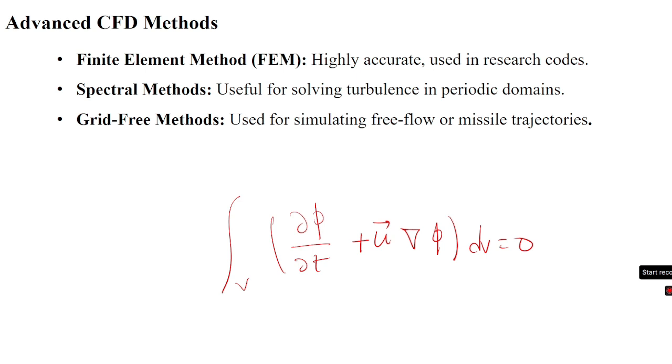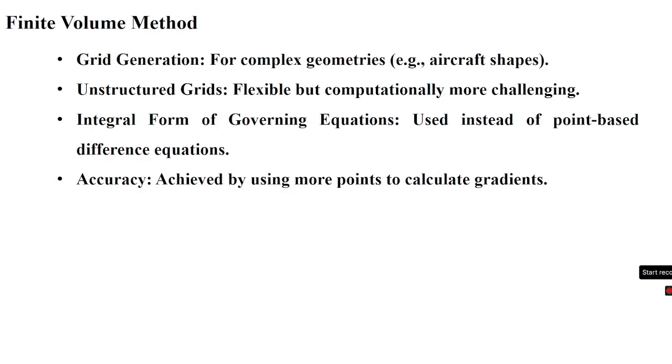So finite volume has some advantages. It can handle any geometry including irregular or complex domains. FVM, the finite volume method, is suitable for aerospace simulation with slats, flaps and other complicated shapes, and can use various types of cells like hexahedron, tetrahedron or prism. But it has some limitations, limited accuracy compared to the finite difference method. Lower order accuracy because it only uses neighboring cells, with no information about distant cells. The solution is often less accurate than the structured grid finite difference approach. That is the disadvantage we have for finite volume compared to the finite difference method.